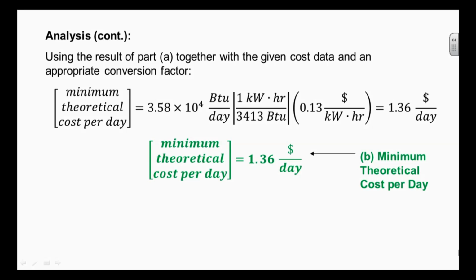It is important to realize that this apparently mixed unit system used in the specification of the problem, while sometimes very cumbersome, is very typical of everyday engineering practice, where heating and cooling loads for buildings are often specified in BTU per minute or BTU per hour, while electricity consumption is measured in kilowatt hours. Therefore, being proficient in unit conversion in the energy field is an essential skill.